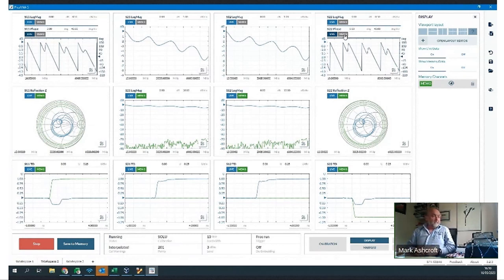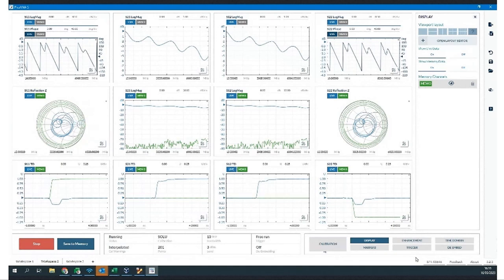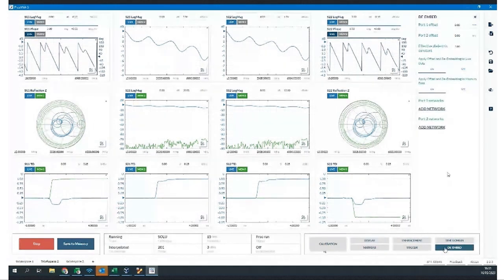Well, the network metrology training kit is a PCB whereby the devices that we're testing are in the center of the board, and they are all sitting on equal length feeders, and we don't really want to measure the feeders because, for instance here, we just cause a Smith chart to be circling round in circles. I can't necessarily understand what's going on there. So let's do de-embed, and let's use reference plane shift in this case.